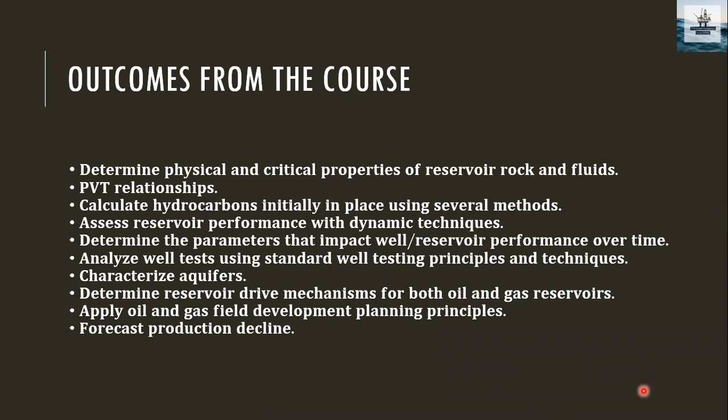Determine the parameters that impact well and reservoir performance over time. There are some sensitive parameters among other parameters which will have a very good driving mechanism towards the production well. That may have a very good impact on the reservoir. That also will be understood. Analyze well tests using standard well testing principles and techniques. We are going to introduce oil well testing and gas well testing, and how these tests, which were in the development phase, will help us understand what the damages around the well are and how to estimate permeability, skin, and wellbore damage. That also will be understood.